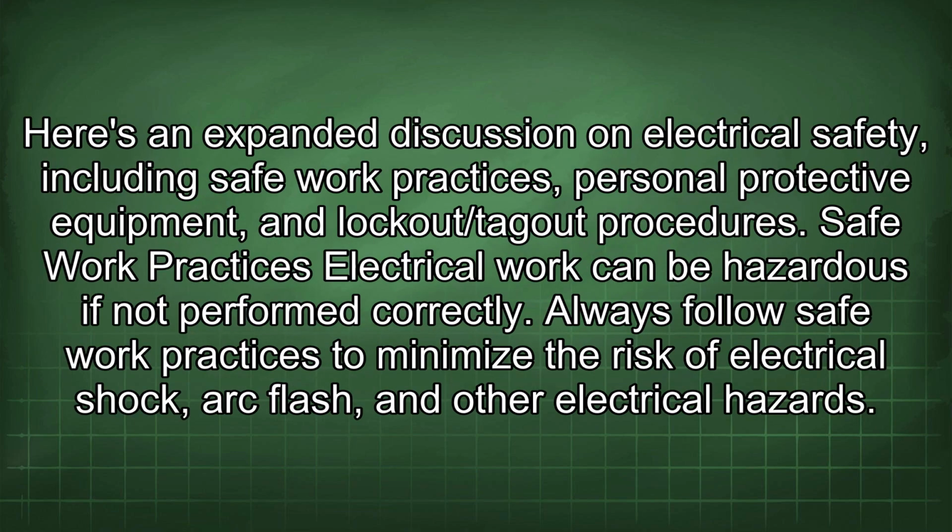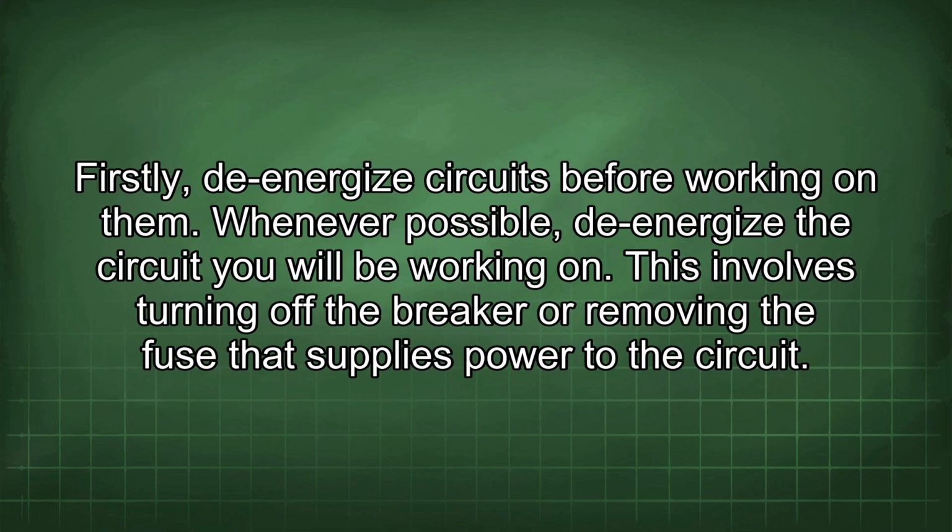Here's an expanded discussion on electrical safety, including safe work practices, personal protective equipment, and lockout/tagout procedures. Safe work practices. Electrical work can be hazardous if not performed correctly. Always follow safe work practices to minimize the risk of electrical shock, arc flash, and other electrical hazards. Firstly, de-energize circuits before working on them. Whenever possible, de-energize the circuit you will be working on.